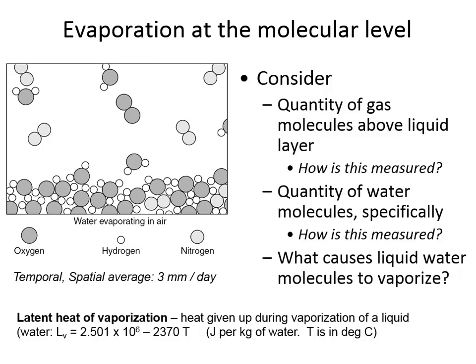And because water requires energy in order to vaporize, the latent heat of vaporization is what limits evaporation in a lot of cases. When the temperature is very low, there's going to be low evaporation because there simply isn't enough energy to drive the evaporation process. For example, the video we watched of pouring water onto a hot skillet, there is plenty of heat available for vaporization, and in fact the water is instantly vaporizing as quickly as it can get into contact with that hot pan.